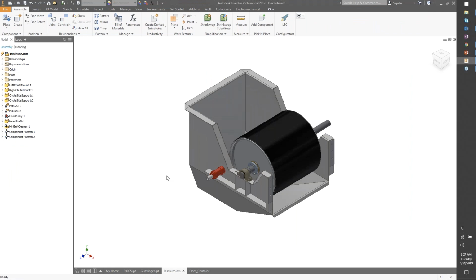I have worked with companies where they'll have an iAssembly that has a series of sub-iAssemblies involved, and those sub-iAssemblies have different iParts involved. So how Inventor works is if you go and change one of those iAssemblies or even one of those iParts, it recalculates the entire assembly. So if you have 20 iAssemblies and those 20 iAssemblies have a series of sub-iAssemblies and those sub-iAssemblies have numerous iParts associated to them, that's a lot of calculation and recalculation Inventor has to do.